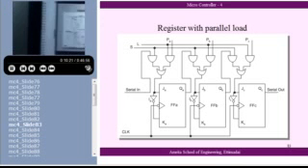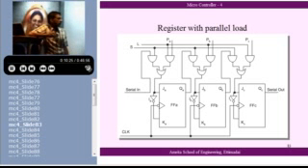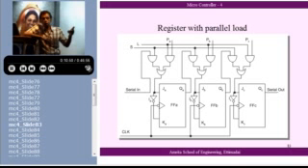Alright? So I have done serial data input by enabling S. It will do serial shifting. If I enable L, if I make L high and S low, please see this. I have done parallel loading. Can you see that? Data is taken from PA, PB, PC lines and loaded here. So I can do parallel loading, I can do serial loading. I can take serial output. By combining this, I can take parallel output.